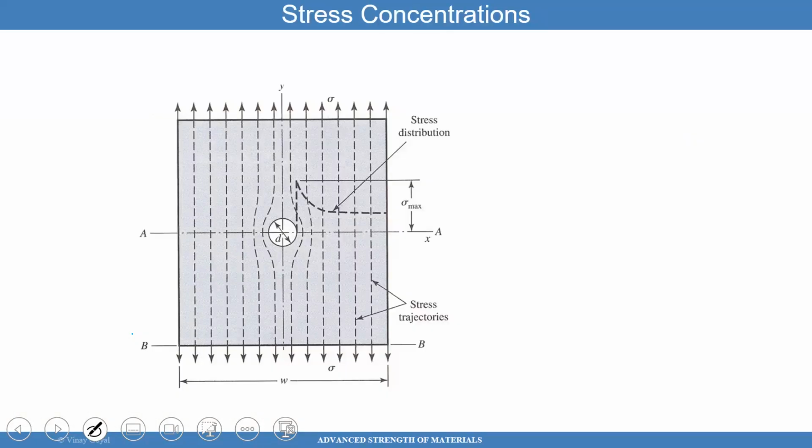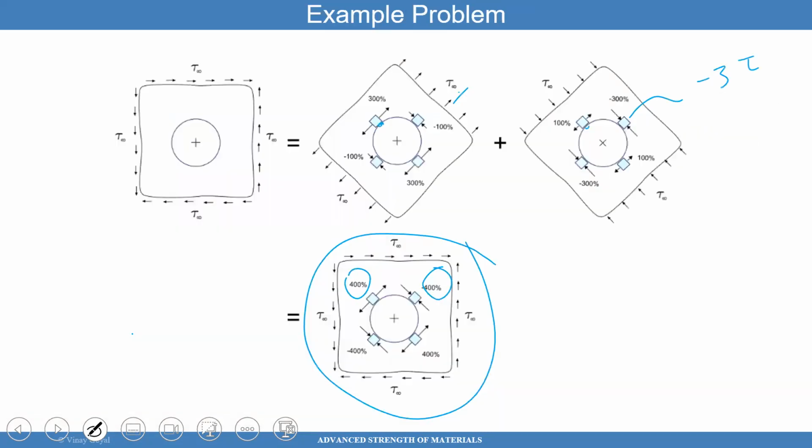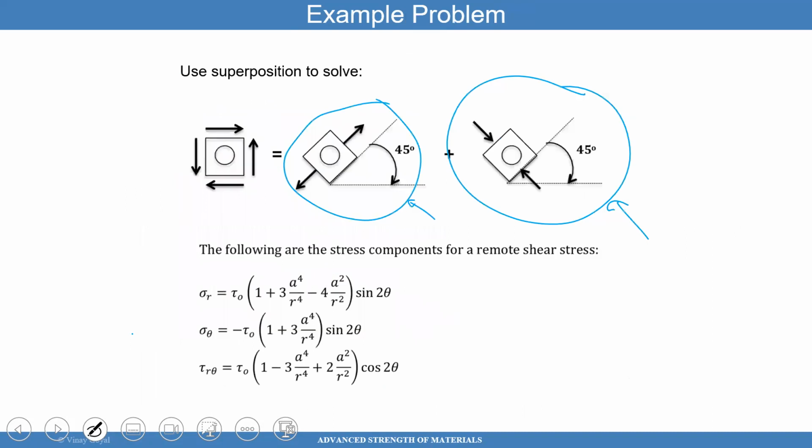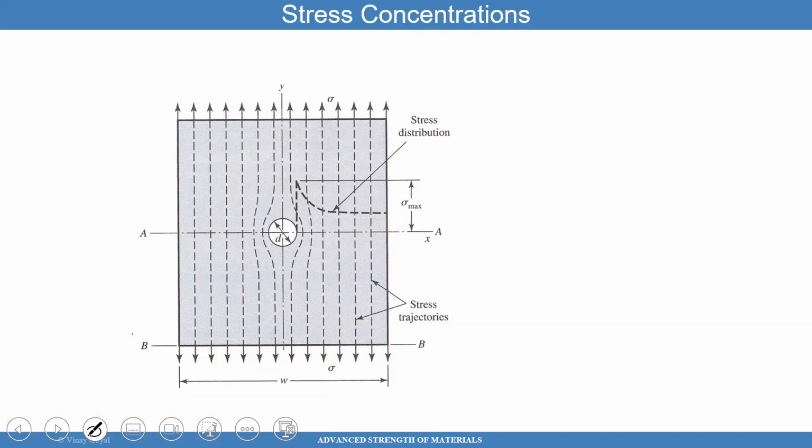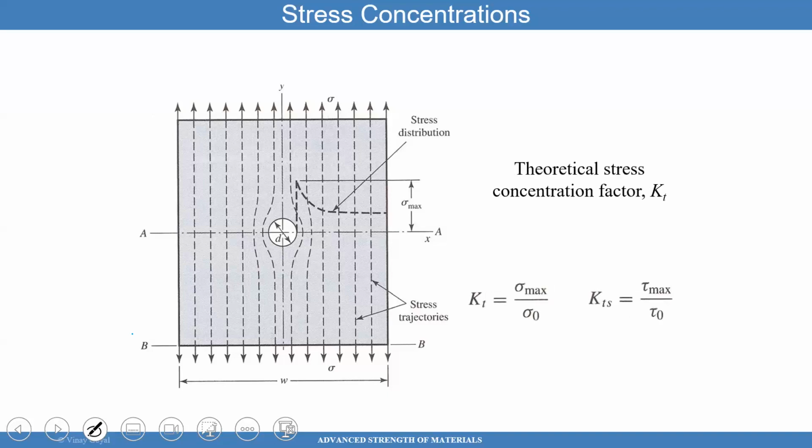So anyway, that's very cool. In summary, we covered stress concentrations, where the stresses drop as you go away from the hole. I'm showing it here. None of the formulas here you have to memorize, because these are just fundamental equations that you can find in textbooks. But you need to understand the theory, what's happening. And I think I was quite clear about what's going on. You have a hole that disturbs the far field stresses in the body of the material, and then you have to figure out where the structure is going to fail, and that's near the hole. And we need to figure out when it's going to fail, and we know that value: 3 times the remote stress is the stress concentration at the hole, the magnitude of that. So we learned that you have that stress concentration factor that occurs.